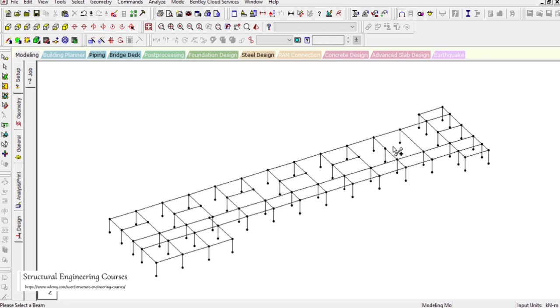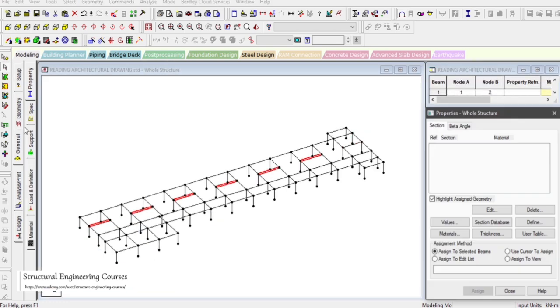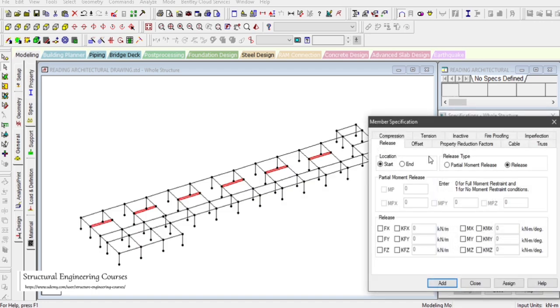On the plinth level there shall not be any structural slab, but by making this beam we are breaking the length of this column along this axis so that the reinforcement shall be less, and all these beams need to be released at the end point. So we go to specifications and we go to beam, start, end, my and mz.